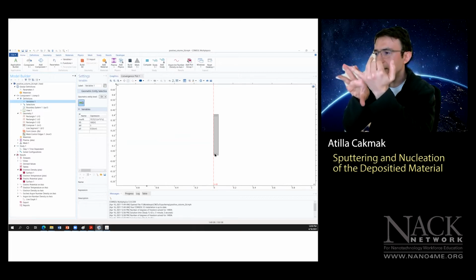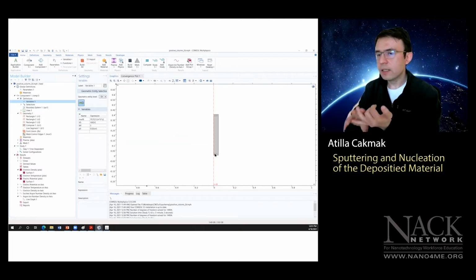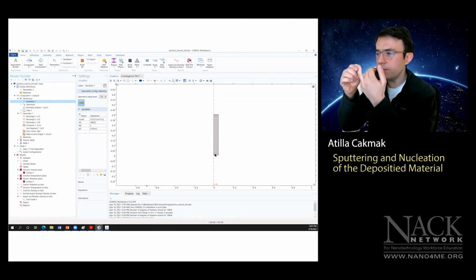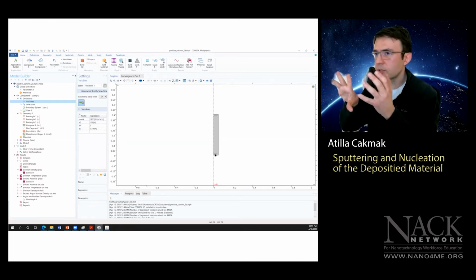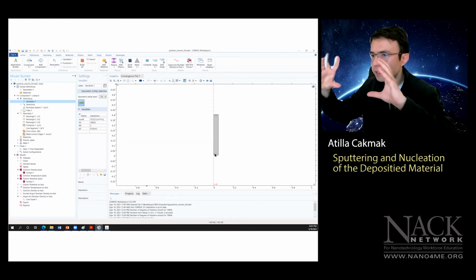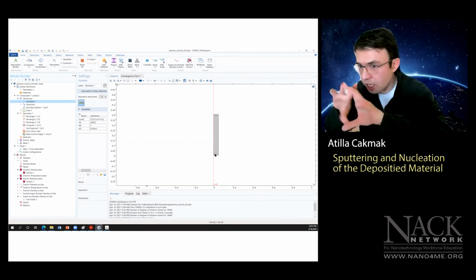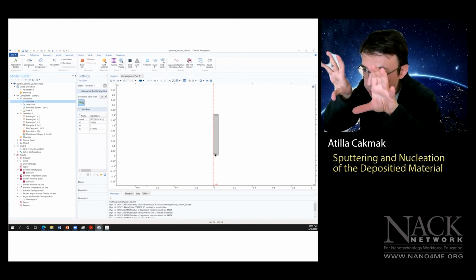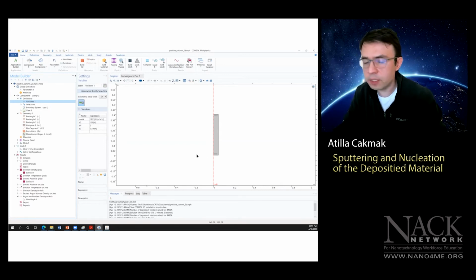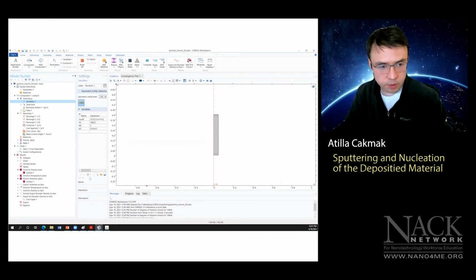We're not able to excite the argon there, right? So that's one reason. Or we might be doing a very efficient ionization and not doing any excitation. That's another dark area. So it depends on how much excitation we are able to do. If there is not enough excitation inside the chamber, those are going to be darker spots. You won't see the plasma glowing in those areas. Okay, so those are going to be the dark spaces. All right, so we've done these three scenarios. Now let's go and do a couple more.